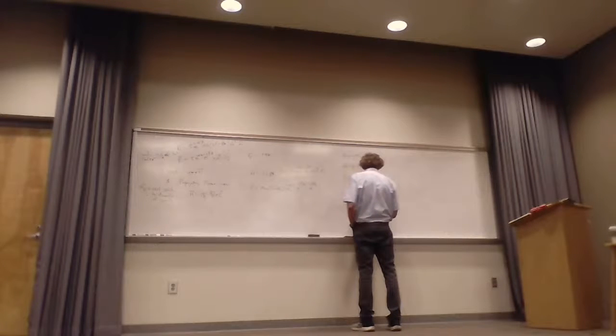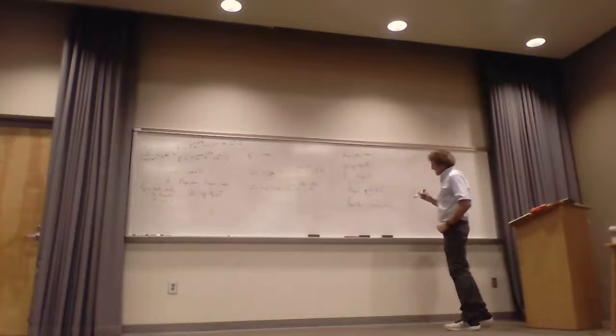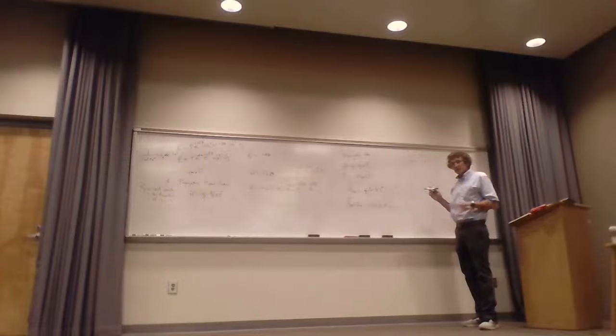It's actually equal to 1/2 the real part of E crossed into H conjugated. I'm going to do that up here. All right. This is going to be for propagating waves. It's not for near fields. This is for propagating waves. It does work for near fields, but there's more to it. All right. If I take a look at this, I'm going to write this out one time and you guys will see it. Y'all with me on this? Can y'all see it okay?